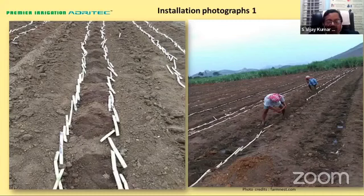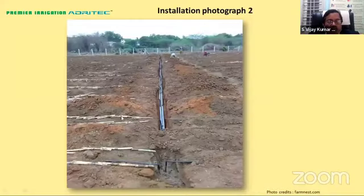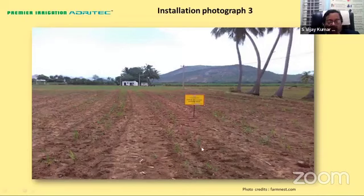You can see the farmer in Tamil Nadu, how he has laid out the cane, and how the setts are being laid out. And then the next step, you can see how the subsurface drip irrigation has been laid out. The submains are in place, and farmers these days, since they don't want kinking of the lateral, use an elbow connection. The submains are buried at a convenient depth, and the lateral lines are totally laid out.